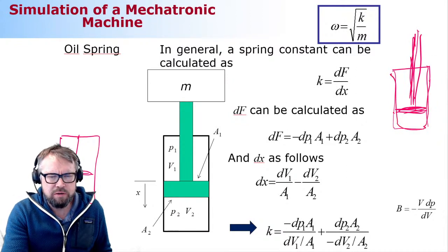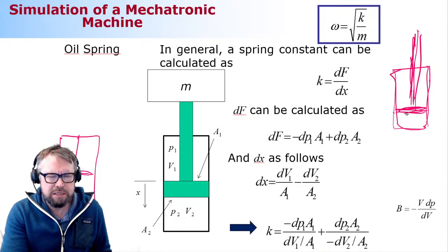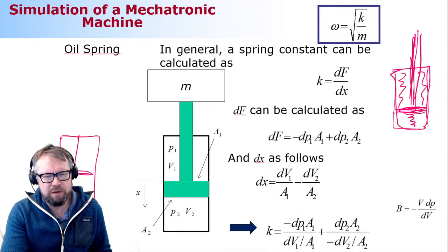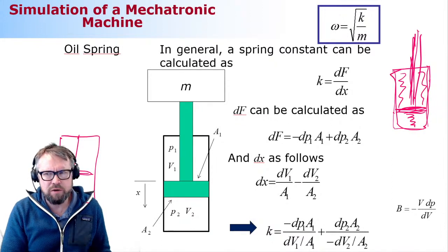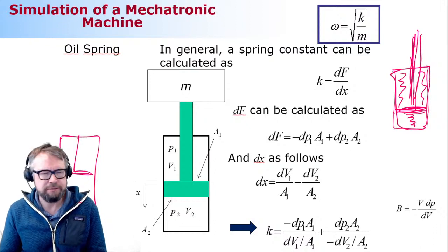This is the cylinder. An analytical representation of bulk modulus is that there is a spring here and two springs here, or one spring, however you want to say. These springs introduce the flexibility associated with this hydraulic cylinder, and there are cases where this flexibility is more significant than the mechanical flexibility due to the deformation of bodies.